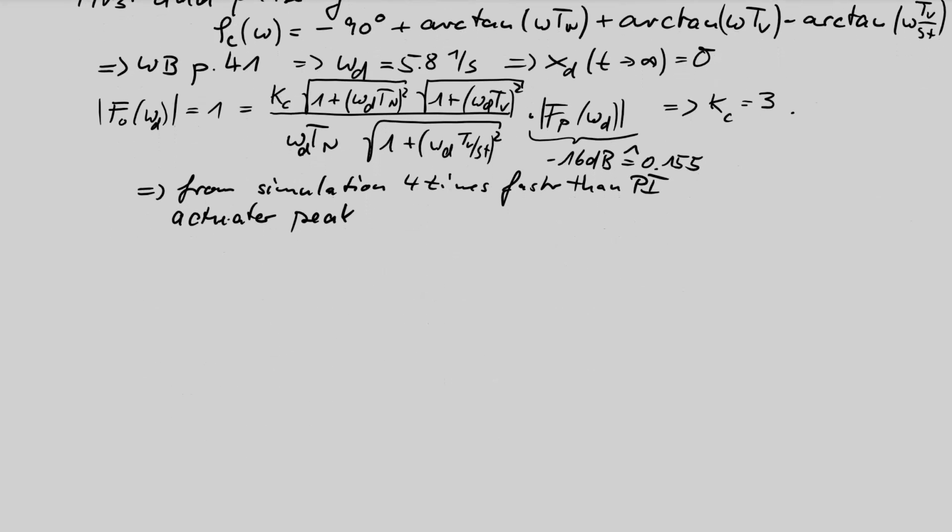Let's compare these actuator peaks. We have the step depths 1, 10, and I want to fill in 2 and 5, and we have here the peak is Kc times step depth. It's a measurement value for the peak value. In the PI case, that is step depth 1, we have a Kc of 0.76 times 1.